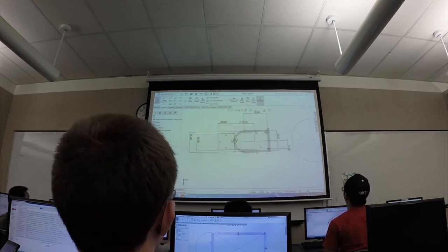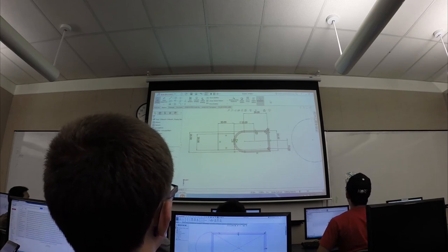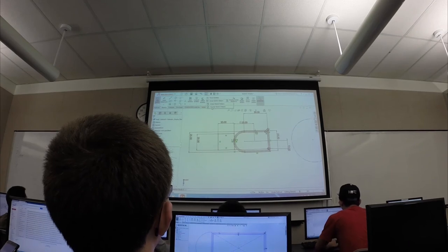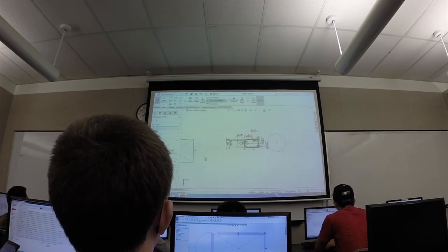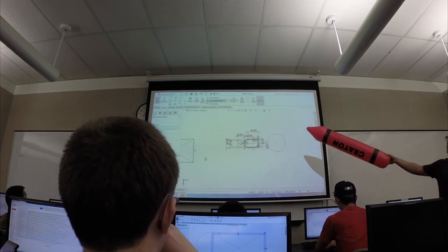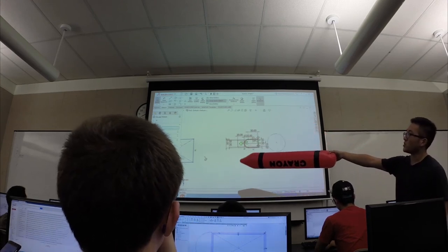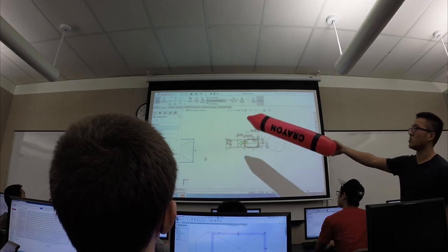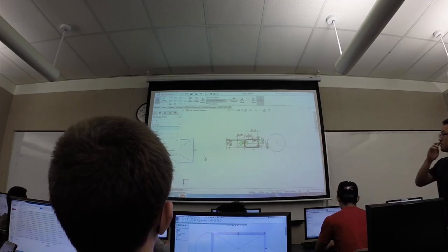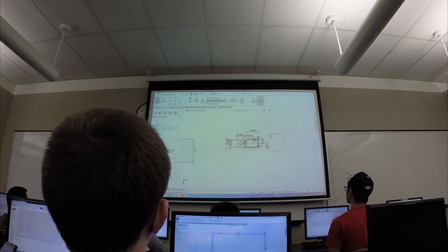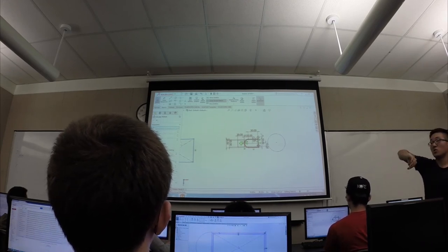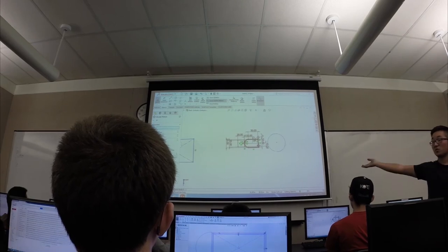Cool, so we're going to try doing a circular pattern. As soon as you select the circular pattern tool, the property manager opens up again, and it wants you to define a bunch of parameters. It's like, what do you want to do with this function? The reason we drew this circle was to tell it, I'm going to use this circle to rotate all that stuff about that circle.